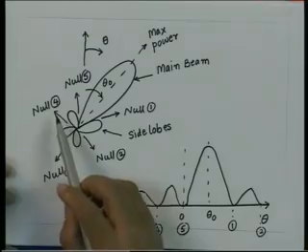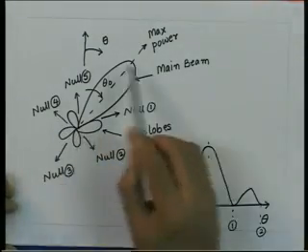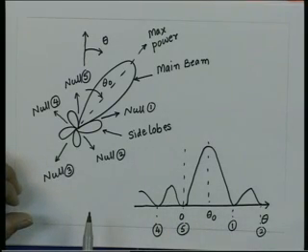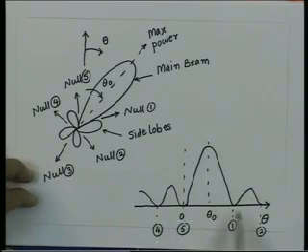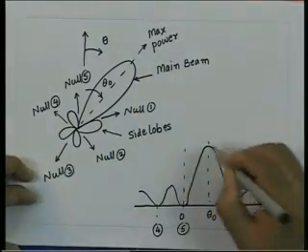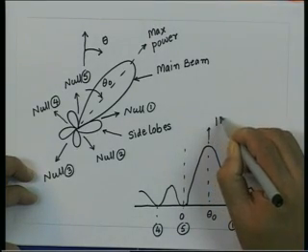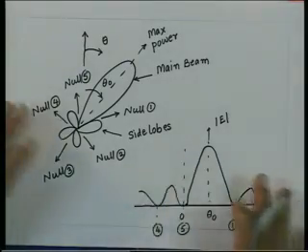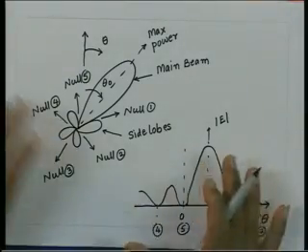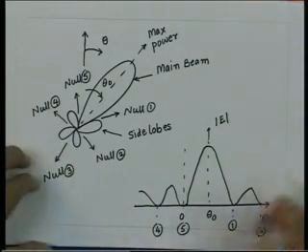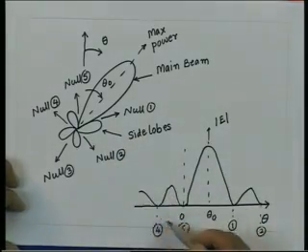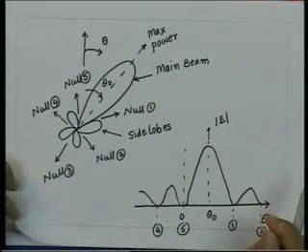So, essentially we can take the radiation pattern, which is actually a polar plot in a plane, as a Cartesian plot, where the angle is plotted on the x axis and the amplitude of the electric field is plotted on the y axis. So, here you are plotting mod of E. Both types of patterns are seen in literature. Some people prefer to draw the radiation patterns like this. Sometimes when you want to do more calculations, drawing the radiation pattern like this comes out to be more handy.